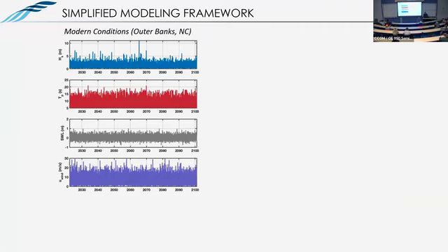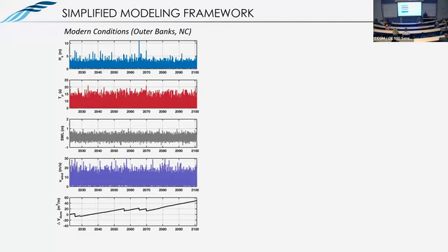All right, so we built a simplified numerical model framework, trying to cover a lot of topics, so I'll go really quickly. But similar to before, we have wave heights, wave periods, basically what our tides are doing, and then in this case, wind speeds. And if we plug this into this simple tool we developed before, we can predict volume change with time of a dune system. We can also predict morphological changes if we had some rules. And I'm just going to focus in terms of volume changes. So the key here is that over this 100-year simulation or out to 2100, the number is positive. So what this is saying is that if we have some forecast that goes out to the future, we're predicting that our dune is net accretional.